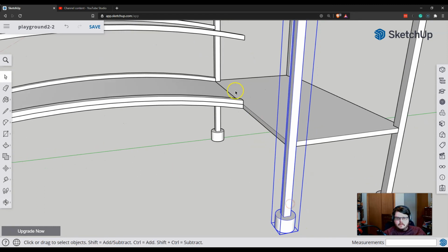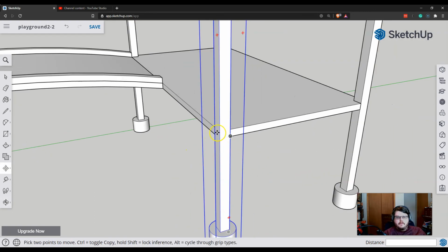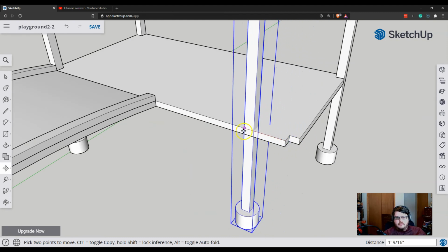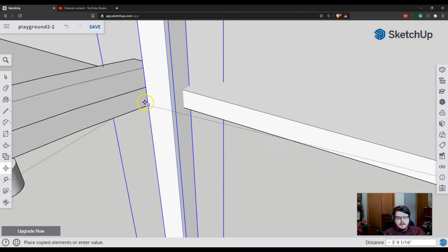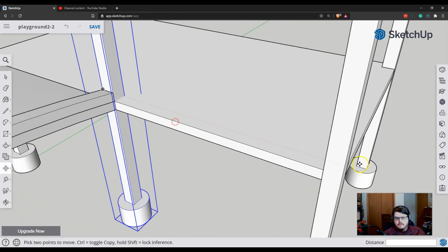that over. So we know that this is 3 inches wide, so all we have to do is move this over so that it's in that same direction. So we want to take the move tool. We will grab it from, say, this corner right here and start moving it in. Hit the Control key to duplicate it, and then we will infer to that corner right there. So that was like the corresponding corner on here. So we grabbed it here, moved it there.